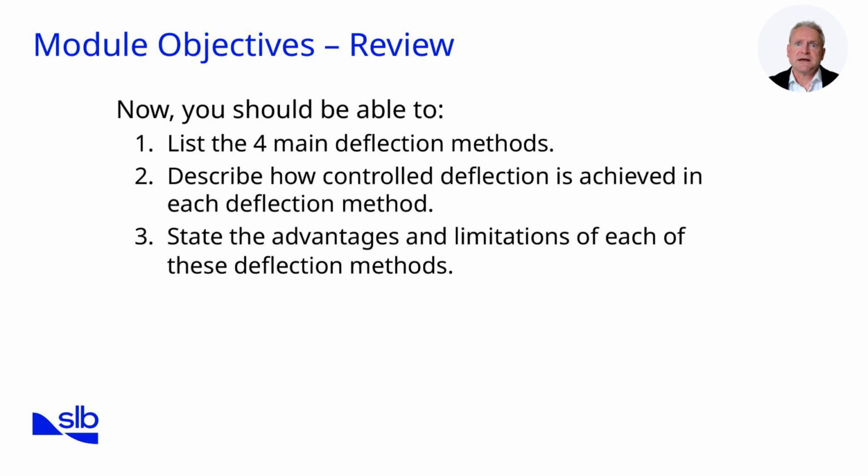Third, you should be able to state the advantages and limitations of each. Whipstocks are reliable in casing exits, but less efficient in open holes. We will continue with whipstocks in the next section before moving on to steerable motors and rotary steerable tools.